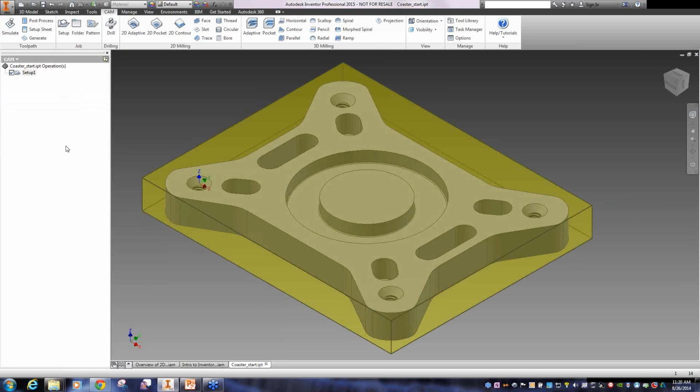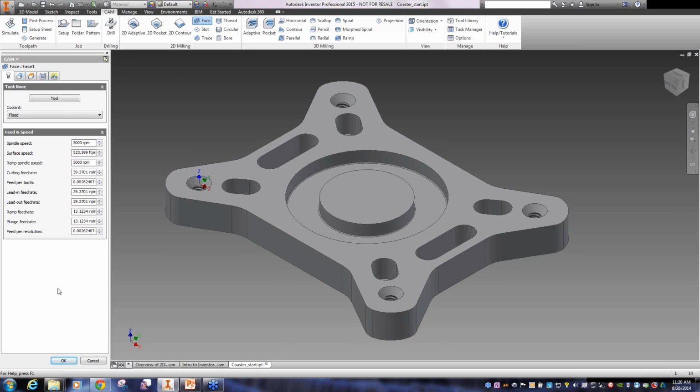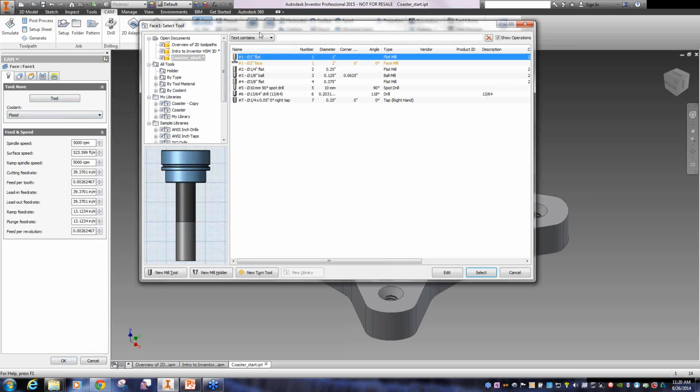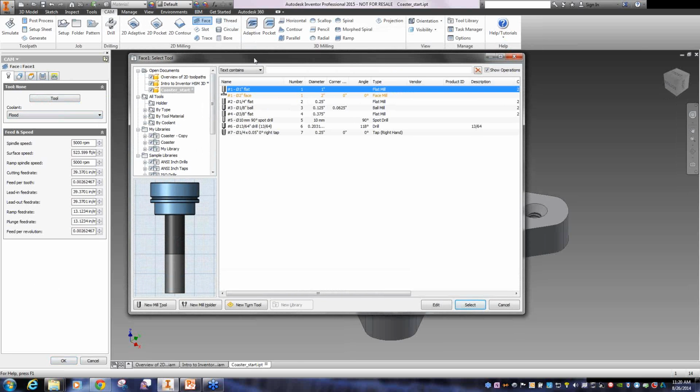you begin machining. The first thing here that we'll do is I'm just going to face mill the top of the part. It brings up a new panel in the browser area, and we work here from left to right also. The first thing that we'll define is the tool, and when you pick on tool, it pulls up a library that actually comes and ships with the product.